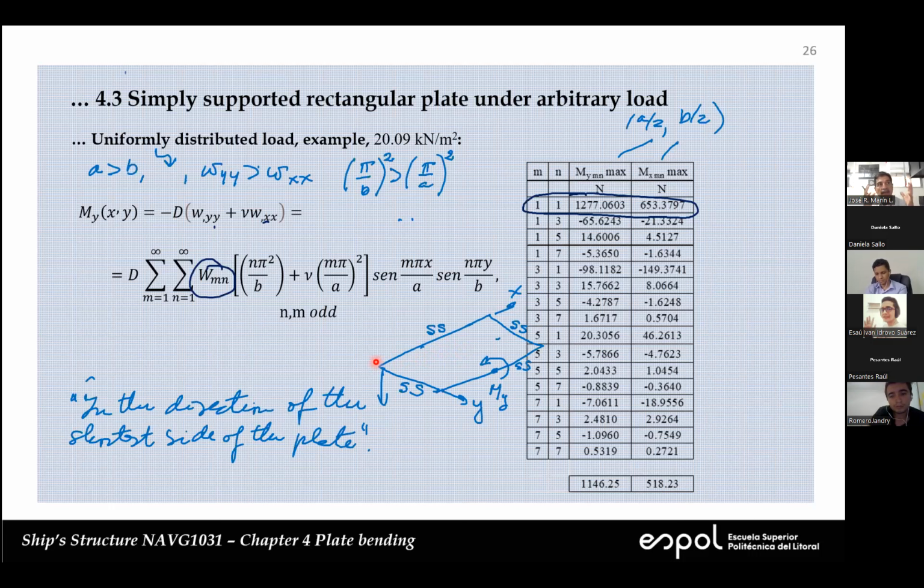Okay, please, you have to be careful because when we go to finite elements, you have the plate bends. On one side, you're going to have one sign of the stress, on the other, you have the opposite sign. And so you have to be careful with how you plot. What do you plot? You plot the stresses in the plate, but on what face?